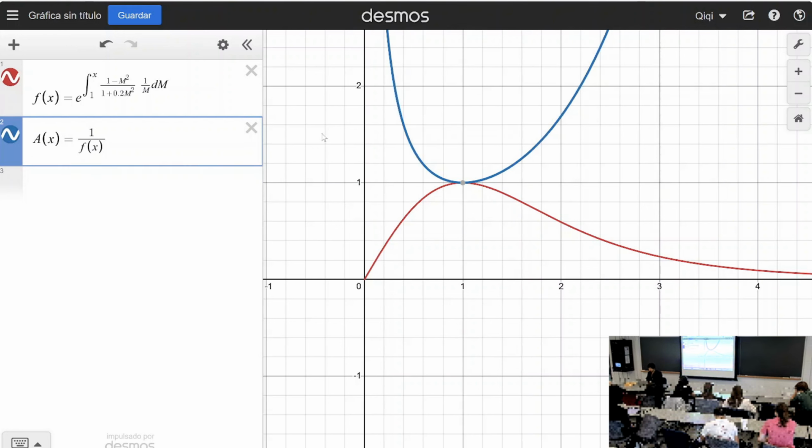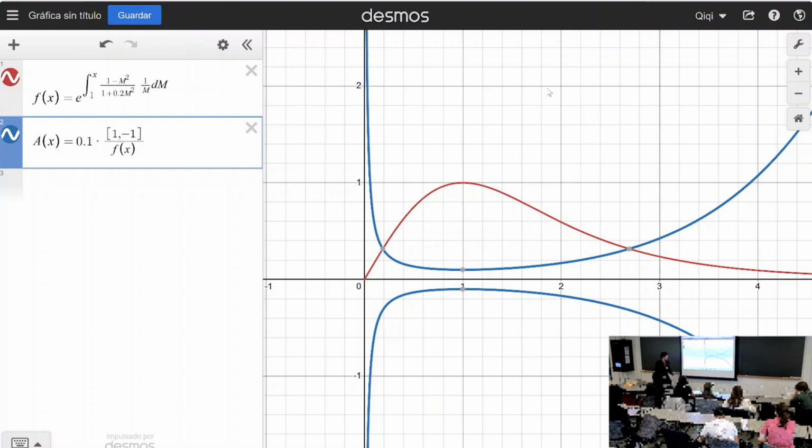That's how a convergent divergent nozzle would look if the Mach number is 0, 0.2, 0.4, 0.6, 0.8, 1, 1.2. If the Mach number increases linearly as a function of x, this is exactly how a convergent divergent nozzle would have to look.